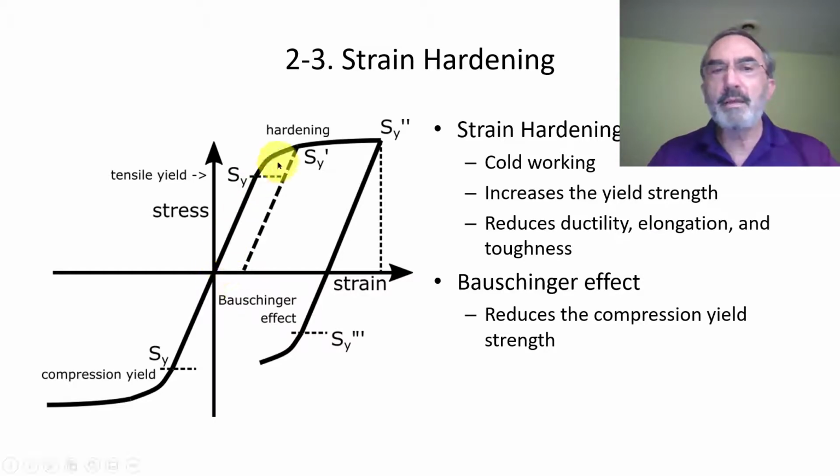So you need ductility, let's say crashworthiness. Doing this trick of increasing the S of Y may not be so great because you're losing some of this elongation. The plot is for a very ductile metal, but not all metals have this humongous elongation. Sometimes you lose 50%. Anyway, you will lose something. But let's say you go crazy, you want to sell your product for more money. So instead of hardening from here to here, you say, no, I'm going to harden more. Okay, you harden all the way there.